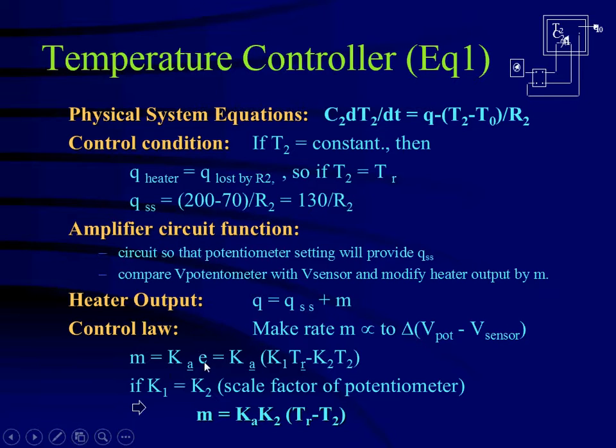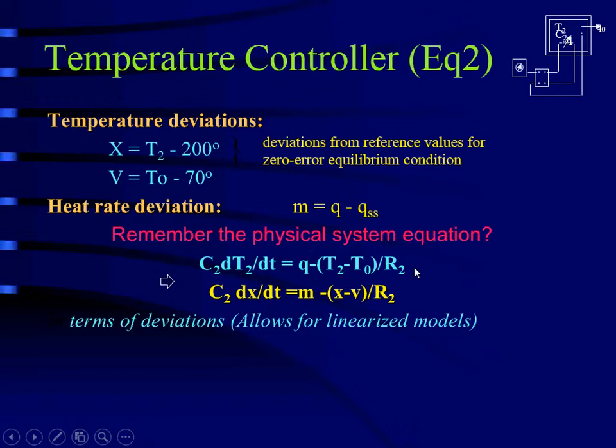Okay, you measure the variable in here, temperature, which gets transformed into a voltage that is compared to what you have originally set up. That comparison produces an error. That error in this case is a proportional control. In other words, you see this is a constant. The more error, the more control. And in here is the disturbance.